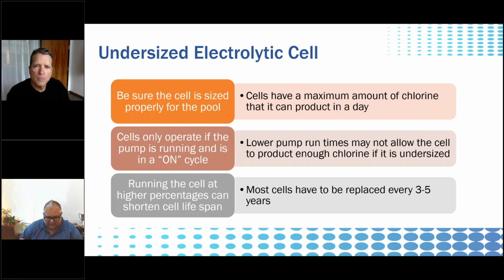But like I said, when we were talking about pH, you can't keep it from happening. You can only manage it as it does. So you're adding pH reducer on a regular basis, which I understand is frustrating to homeowners, but there's no way around that unless you automate it. If you're in a commercial situation, you can automate it using an acid feeder or a pump or something along those lines. Those are good options to not have to hand feed it all the time, but ultimately it's just part of the process. And it's one of the most frustrating things, because people want to say, it's a salt pool, I don't have to do anything to it. And that's just not accurate. You do have to do things to it, and adjusting pH is a constant battle.